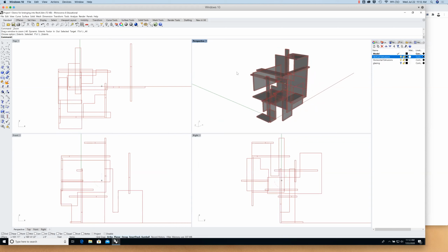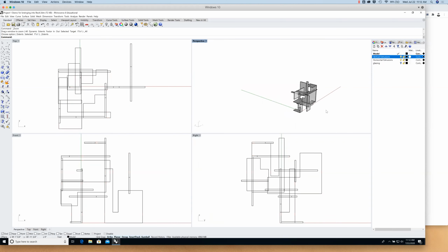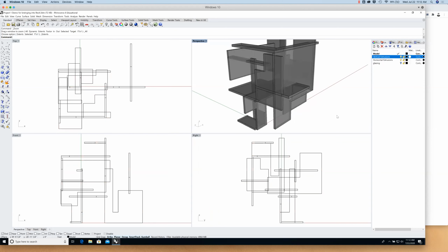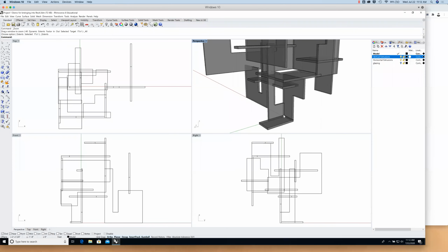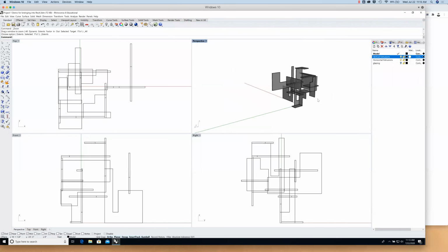Some of you might still have this grid on, and you'll see that also on your screen, which is perfectly fine. But that's what I did. I basically just moved this over so it's centered up in the world Cartesian space. What's important about that is that now that we have the 0,0,0 point, when we import it into Revit, it'll also import at that 0,0,0 point in Revit. So it'll be centered up in our site plan view and in our 3D views. That'll just be really handy. It won't be off to the side somewhere, off in space in some weird willy-nilly position, but we'll have it nice and centered.